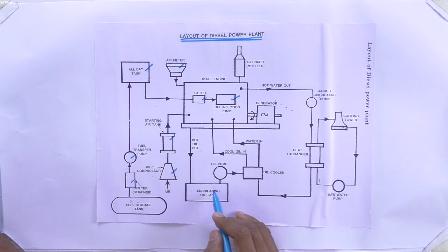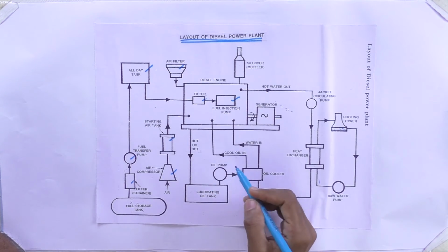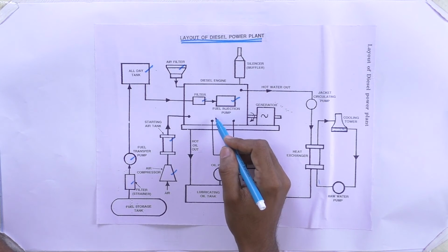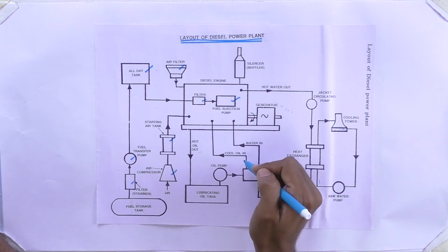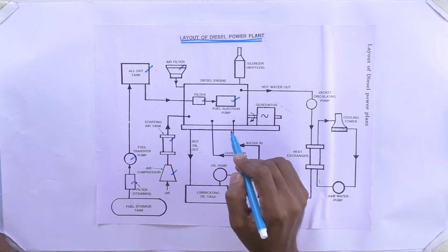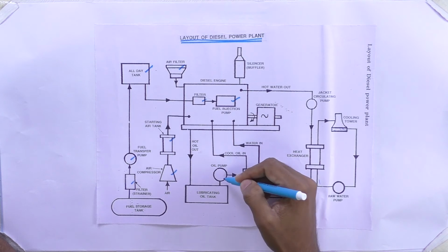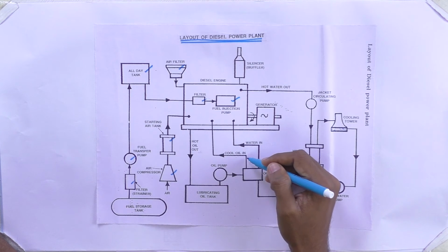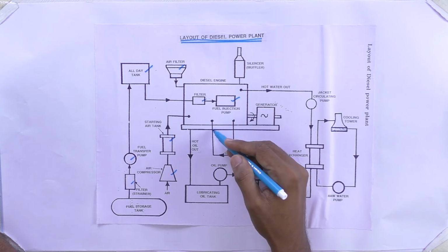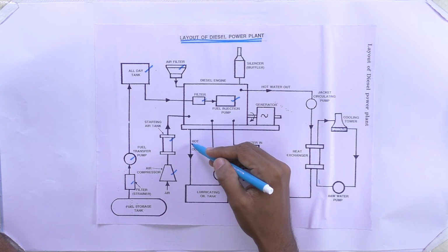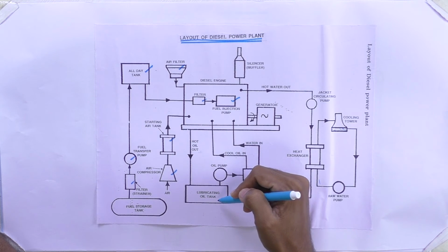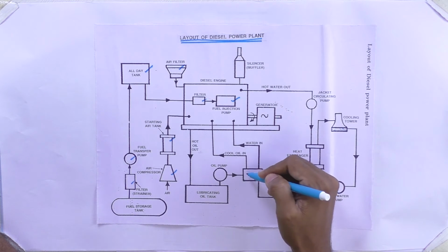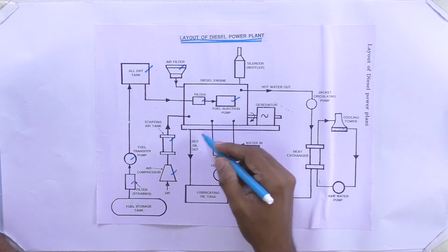If you consider the lubricating conditions, the coolant oil is used to avoid friction between two parts, so we are using the oil as a lubricant as well as for cooling purposes. The oil is stored in a lubricating oil tank, and the oil pump pumps the coolant oil to the engine. The output is hot oil, which comes back to the lubricating tank. That hot oil may get cooled with the help of some water arrangements here. So these are the things that happen frequently.